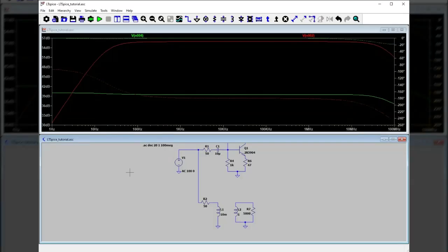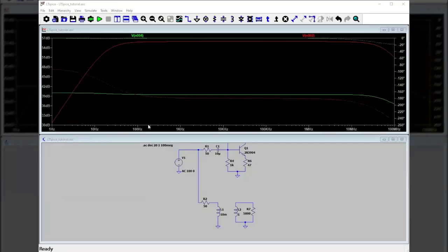All right. So pay attention here because you won't see this box. Edit. Spice directive. Select that. It'll open up a little box and you're going to type what you see appear on the screen here in just a second. K, capital K, probably doesn't matter if it's capital or not, and then some number. I'm going to use 1. It's the only one in the schematic, so why not?